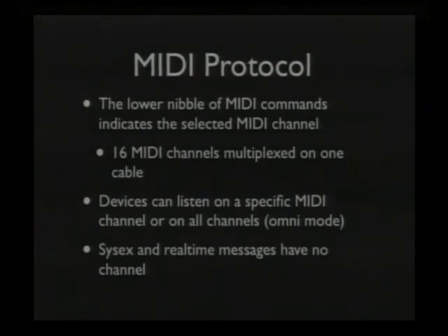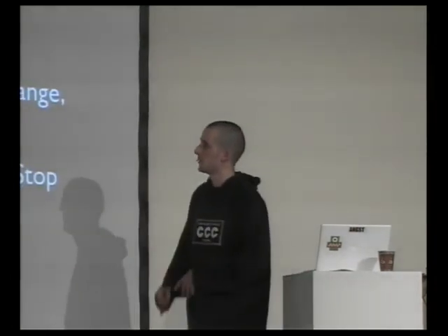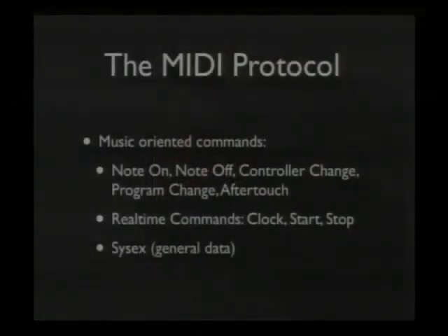And there's this thing called system messages, which is further split into real-time messages and system-exclusive messages, I think they're called, which are used to send system information which is not musical. So those are the commands you have for music. You can send note on. For example, when you press a key on a keyboard, it's going to send a note on, and when you release the key, it's going to send a note off.